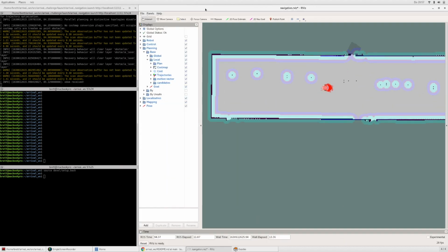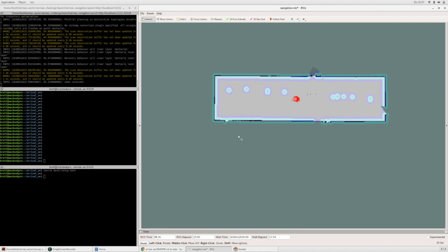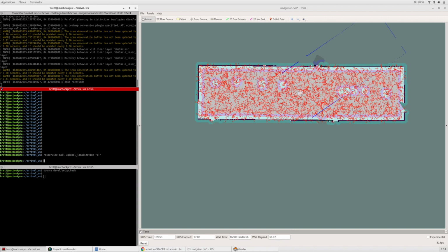The assumption is that this world, or this map, has already been generated as a test scenario. However, this assumption can be bypassed by creating the map if desired. So we can go ahead and localize within this map by calling the ROS service call, at which point we'll initiate the AMCL particle filter.